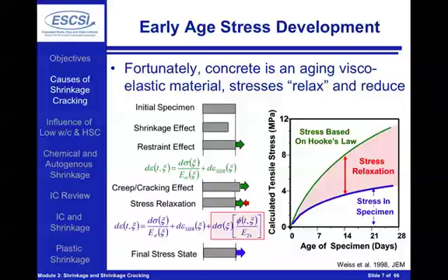in concrete we actually have what's referred to as an aging viscoelastic material. Now this viscoelasticity is important. This essentially allows the stresses to be relaxed out of the system. So if we pull on a system and we hold it at a constant deformation, over time, those stresses will actually be reduced. This is a lot like pulling a rubber band, leaving that rubber band over a longer period of time, and you'll realize that rubber band has sort of become stretched out. That stress relaxation in a rubber band has to do with the polymer chains essentially untangling. In concrete, this has to do with essentially the CSH sheets sliding over top of one another when there's water present inside of the system.